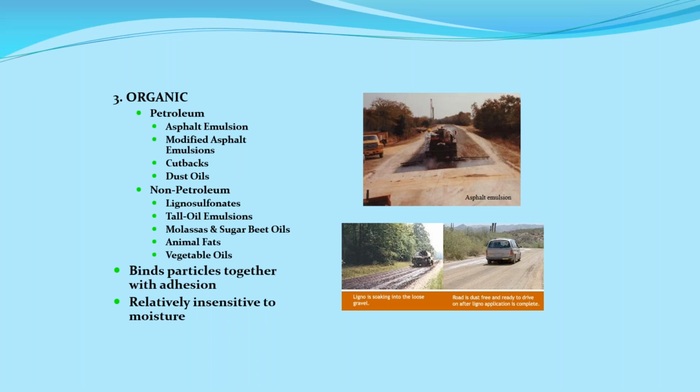Generally, what we'll find is if we use a mag chloride or a calcium chloride, we'll actually see it pick up some of that moisture in the nighttime cool air, because our humidity will come up a little bit and it can gather some of that moisture. So I try and steer people away from the sodium chloride for that reason.